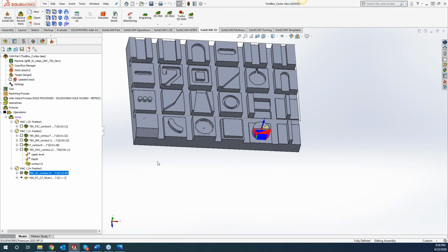I think Tim's on the right track with the geometry selection, but maybe highlight the difference in coordinate system as well, because you've got one coordinate system that is normal to the face that you're cutting, and another one that is on the flat of that cylinder, probably normal to the table, but not to the cut face. Correct. And sorry, Tim, when I was switching back and forth, I didn't quite hear what you said about the geometry. I think the reason this last toolpath couldn't be used on the first one is that it wasn't a circle. Yes.